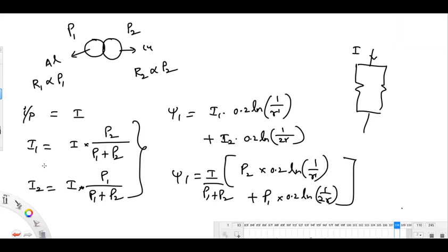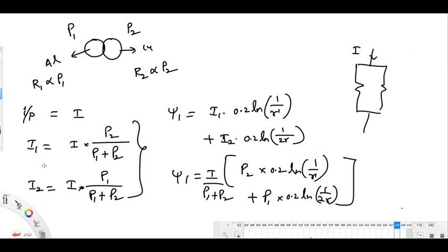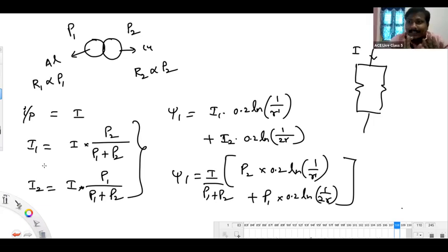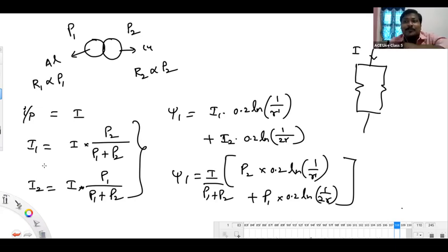Yes. You can't avoid reactive power. Some people will say, I will make the net reactive power 0. Yes, that statement is correct. But what you should understand is, you have both elements there, inductor and capacitor. One is absorbing, the other is delivering, and those two are exactly matched, so that it need not draw any other reactive power from the source.